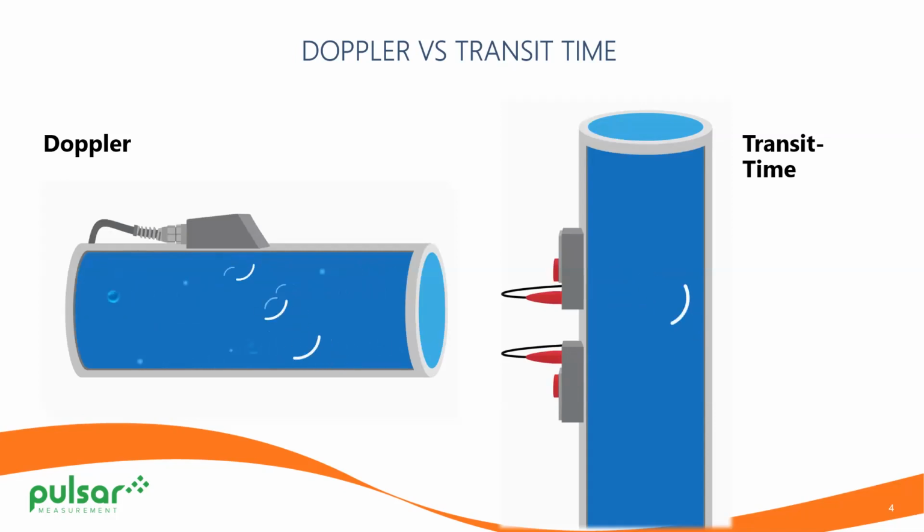It's targeting that, and as the particulate accelerates and moves away, the Doppler signal is going to change. That's going to be an altered frequency. So it's going into the pipe at 640, but as the particulate gets further and further away, it's returned at a different frequency. That difference is proportional to the flow rate. And that can be air bubbles, it can be slurries, it can be anything from rocks and sand, just about anything that flows through a pipe.